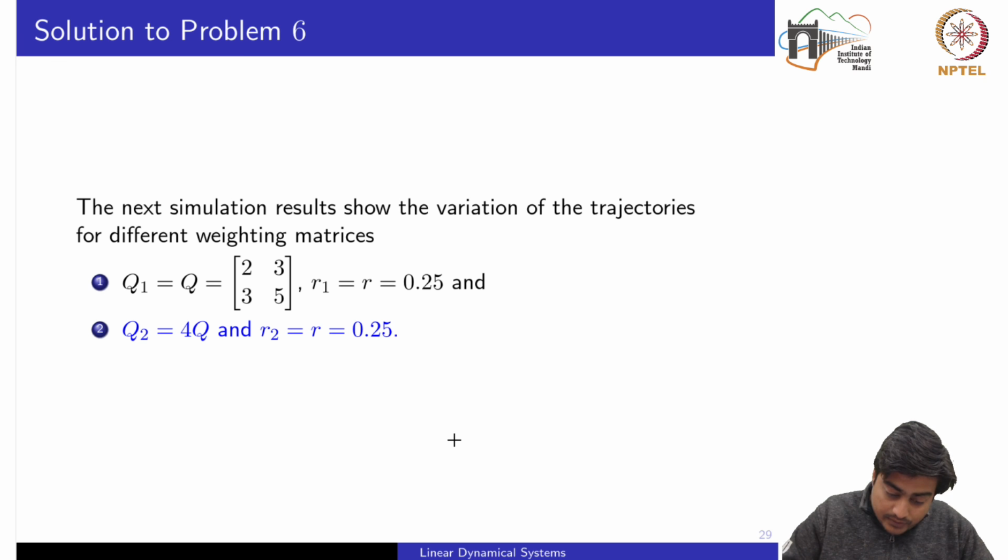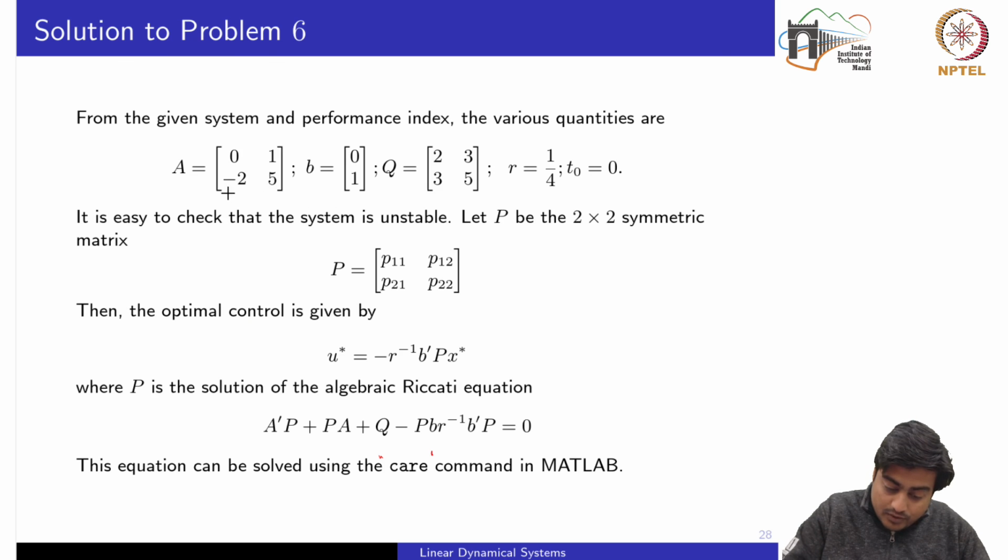Right, so now we would go directly onto the simulations, because this information A, B, Q, R is already given to us. Now using this information, by using the derivations we had seen in the lecture slide, you can compute directly this control law, where P you can compute by this one. So A and B are fixed because of the system dynamics. What we can see is the behavior of the closed loop system with respect to Q and R, which are the state and the input weighing matrices.